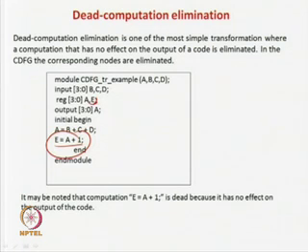So, A is remaining a variable in his case, but it is not an output. He eliminated that E is not required to be an output, so he eliminates this here, and also, as the output A, E was there, he also eliminated it. But the other definition that states it is a variable, he might have forgotten to eliminate, and also he might have forgotten to eliminate E equal to A plus 1. So this code unnecessarily will be in your computation, and it will lead to an adder and a register for E, unnecessarily hanging and making your area overhead. So you can actually eliminate this part and this part.